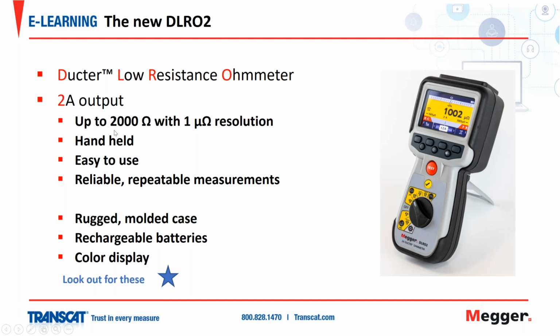These first 4 bullets here are based on key customer requirements, based on our research that we've done. Just a note on the 2,000 ohms, someone might ask, well, why would you need to read something that high? We're talking about very low resistances. The answer to that is that it's useful in production environments for testing component values, and it can also show the difference between a really poor connection and a complete open circuit or incorrect connection. Then these last 3 points are just key characteristics of the DLRO2. It's got a rugged molded case, rechargeable batteries, and a color display.